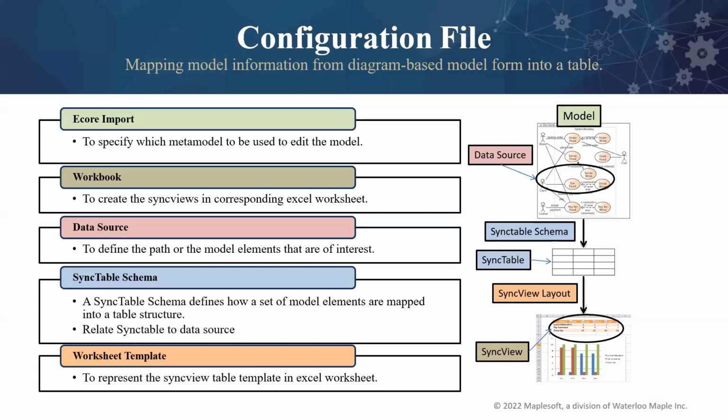So for the level 2 subfunction, give me again the name and description and so on. This information goes into the sync table schema. Once we create these 5 modules, when you launch the config file and connect to the Capella model, you will be able to see the information being captured, and it will work bidirectionally: any updated information from Capella can be seen in the Excel view. In the same way, if a user modifies the Excel view and saves the changes back to the Capella model, you'll be able to see this as Capella elements itself.